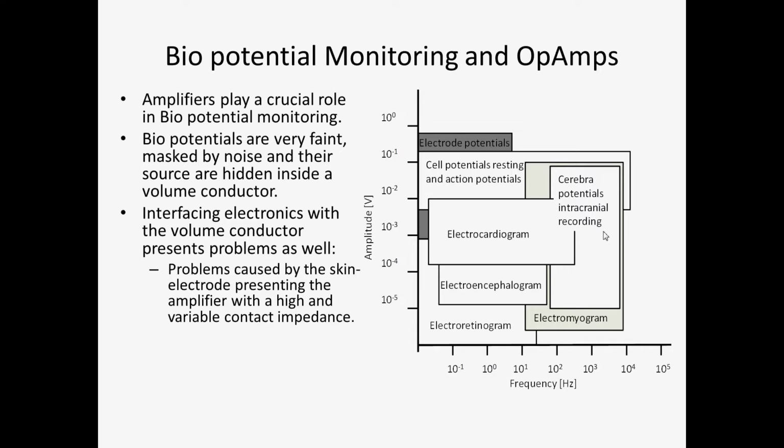Again, this figure, I'm not saying you should print this figure, laminate it and bring it, put it in your wallet together with your beloved ones, but you just need to understand that amplifiers actually play a crucial role in biomedical or physiological recordings, because all the physiological signals are extremely faint, extremely small, and most importantly, some of the sources are protected by skin and tissues that we need to interface with, electrodes, pipette, needles, whatever it is, but we need to overcome all these possible sources of noise and imbalances in the input impedance.